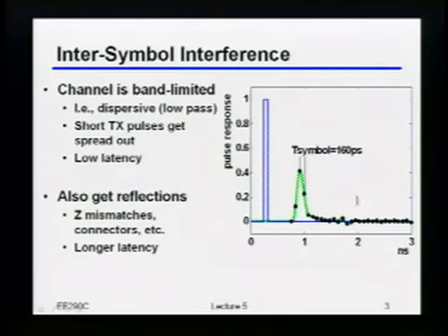Right? Those are basically reflections that took additional time to propagate down the channel and then finally show up at the receiver. Okay, so a fairly common type of link response would be something where there's this dispersive, close-in kind of response. And then sometime later, there are these reflections that come in and cause a little bit of additional ripple or weird-looking behavior there. Okay?